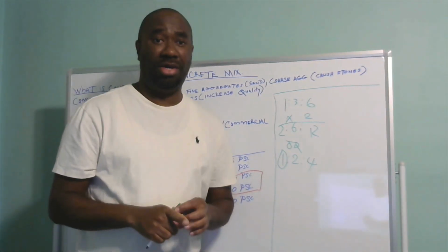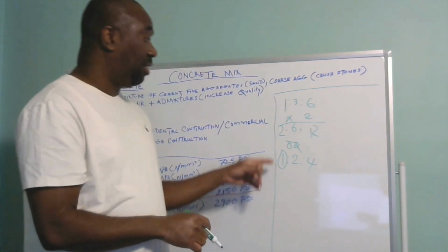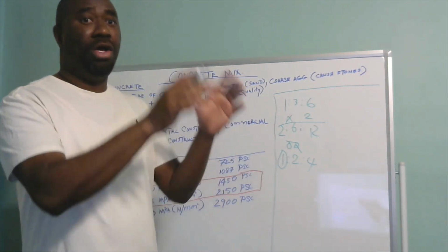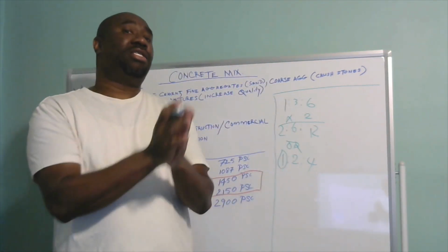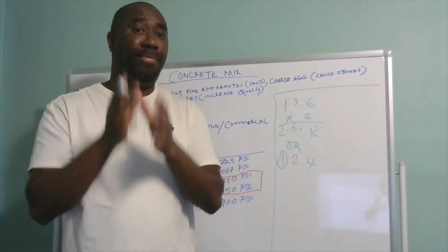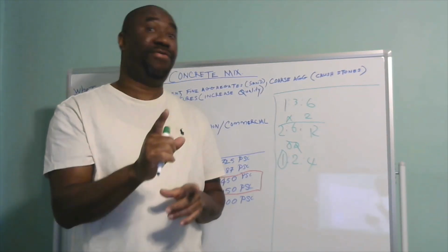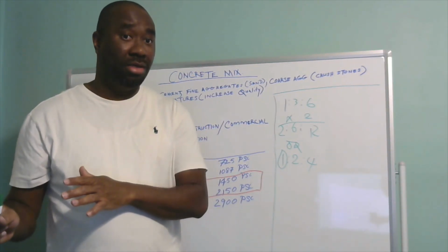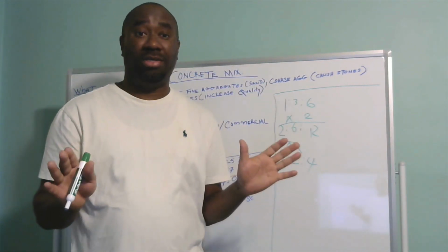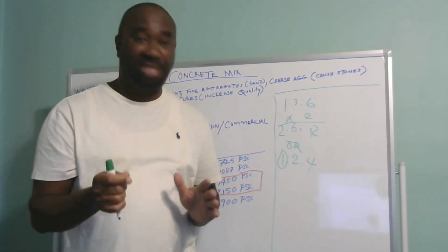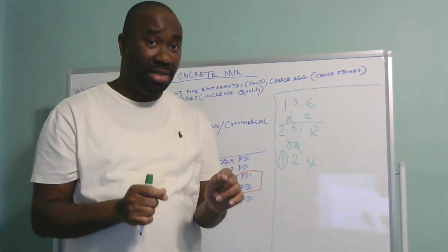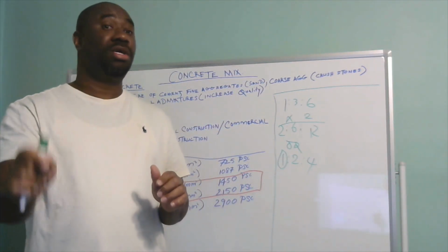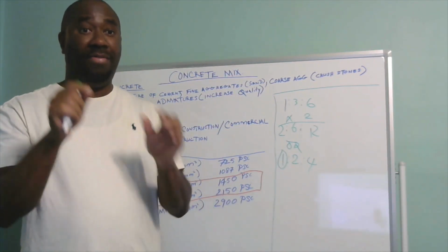And from my information, when I was a site manager, I know that it takes 2.5 bags of cement to fill a barrel. So if your measuring apparatus is a bucket, it is 1 bucket of cement as against 2 buckets of sand as against 4 buckets of coarse aggregate. Whatever your measuring apparatus is, if you're using a teaspoon, it's supposed to be a teaspoon of cement as against 2 teaspoons of sand as against 4 teaspoons of coarse aggregate. And that is very, very critical.